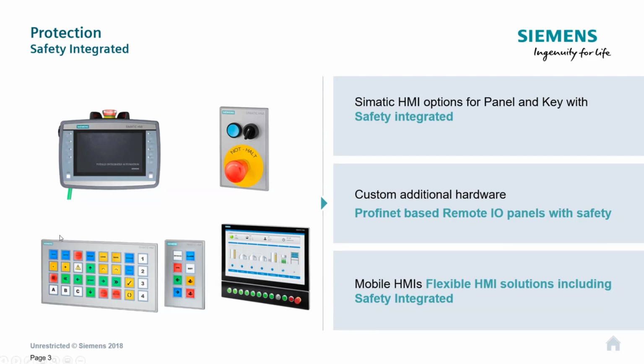So we can have connection boxes dotted around the place where we can connect the HMI into and decide whether the safety emergency stop that's on the device is active or inactive. And this works depending on the connection box with a safety PLC or a traditional hardwired safety system as well. So very flexible in design as well.